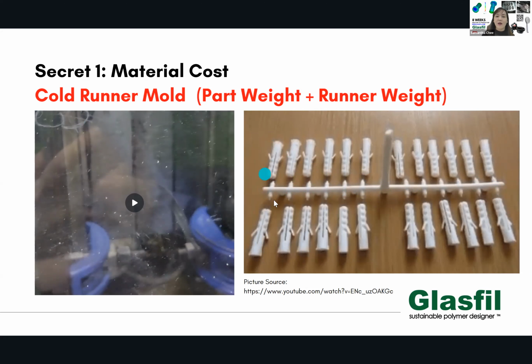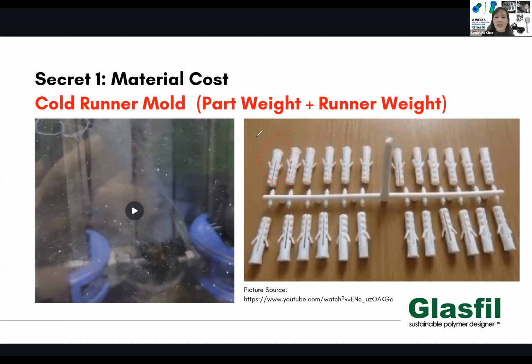If you look at this particular product, which part is the part? This is the part. This is 1, and this is 2. Some people will wonder, how do I get my wall plug? Basically your wall plug is injected using plastic injection molding, and it is developed in this manner. Very simply, this is 1 wall plug, this is 2 wall plug, this is 3 wall plug, this is 4 wall plug. And you notice, what is this portion? What is this thing? This is what we call the runner. What is the function of the runner?